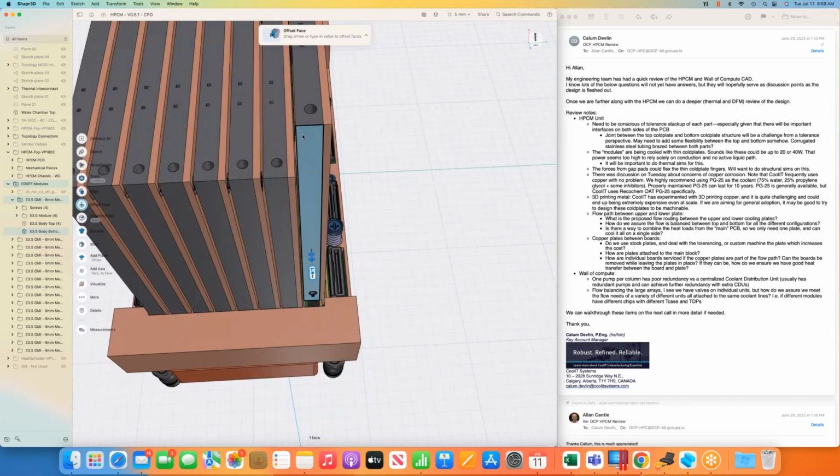Or the aluminum body is a cold plate, and there is a thermal mate between the lid and that cold plate itself. This lid doesn't need to be copper necessarily. It could be an aluminum lid, but that will depend on our thermal analysis as well. I see. Thank you. At the moment, I'm assuming it's a copper lid, but not necessarily.